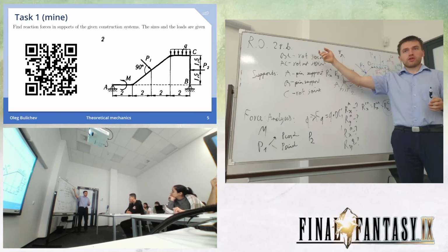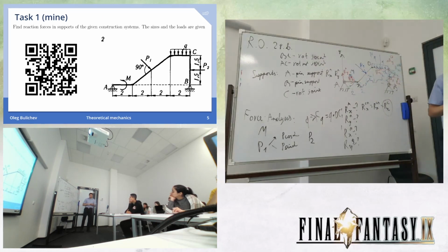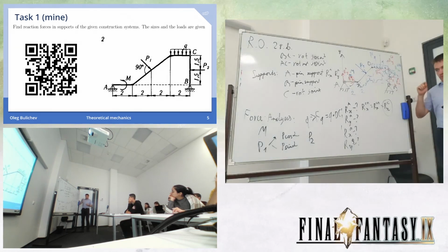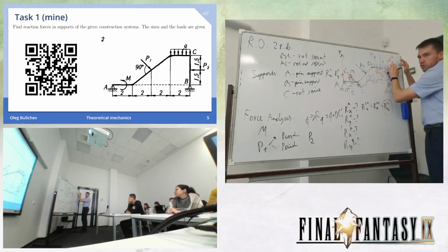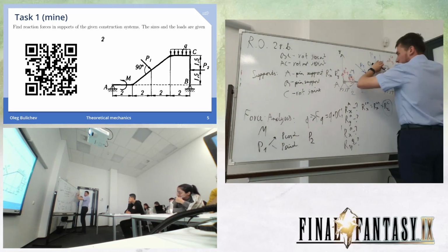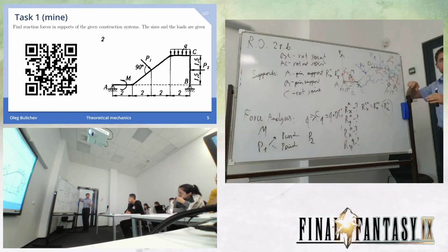How many equations do we need to write there? For each body in general we need to write 3, so in general we have six equations. But in our case, some equations might cancel out. Actually there are more, because some equations are constraints. When we talk about one body, we assume that it's isolated from others. We don't know anything about the others. After this, we need to put extra equations which show that it's constrained.